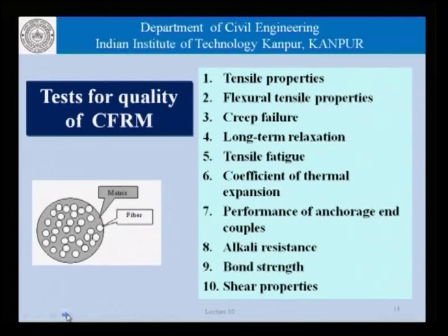Now, let us try to look at the tests for quality of CFRM. It is not only the tensile properties that we are bothered about, we also need to look at flexural tensile properties, tensile fatigue properties, creep, long term relaxation, coefficient of thermal expansion, performance in anchorage and couplers, alkali resistance, bond resistance and shear properties and so on, if we really want to apply a CFRM such as this as reinforcement in concrete structures.